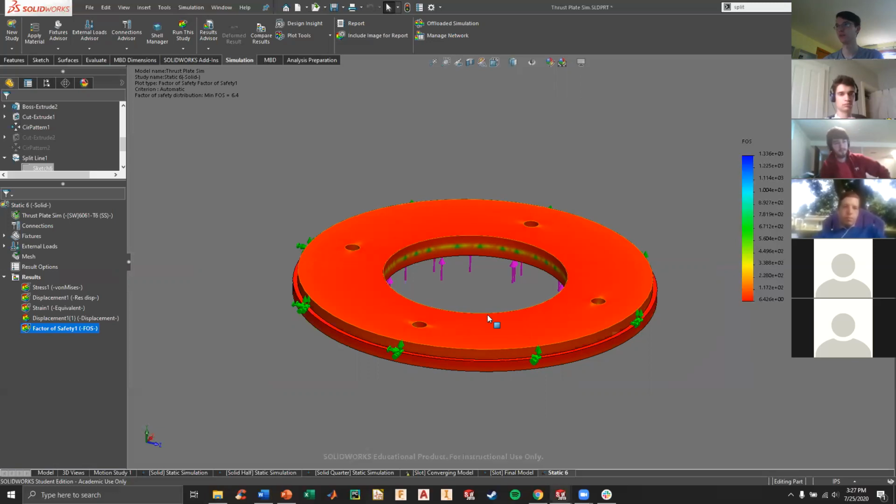For the metal parts we're going to be working with, they have pretty high yield strengths. So it's an issue if we're plastically deforming aluminum in our rocket. And if we were going to make parts out of plastic, then we would be more concerned about the nonlinear dynamics of what's happening. But for the stuff we're making, static studies are perfectly acceptable.